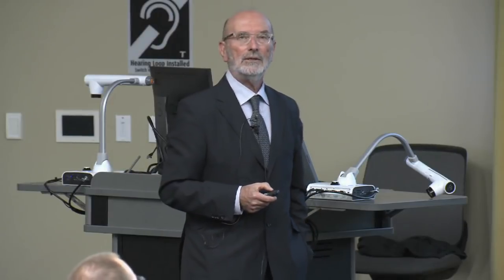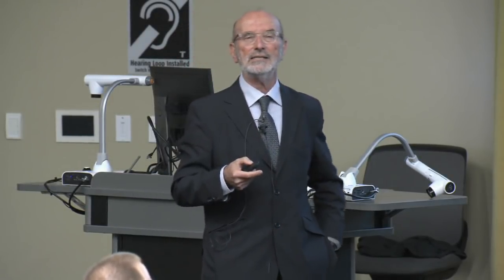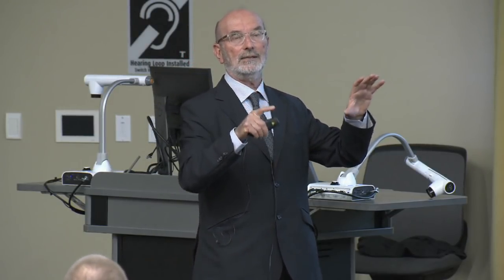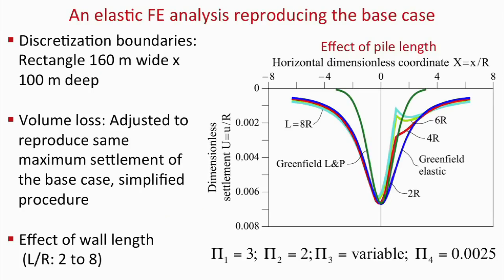And we also were interested in checking this solution against a better solution. Well, better in the sense that you use, for instance, in numerical analysis. And if you have to compare elastic approaches, then imagine a finite element under elastic conditions. So this is the case of this comparison. This is not so easy to do immediately, because you have to check that, for instance, the volume loss or anything may be used to select the same case. And in this particular case, what we did was to ensure that we reproduce the maximum settlement of the simplified procedure and the maximum settlement of the elastic solution. So just to have a reference which is common, which makes some sense.